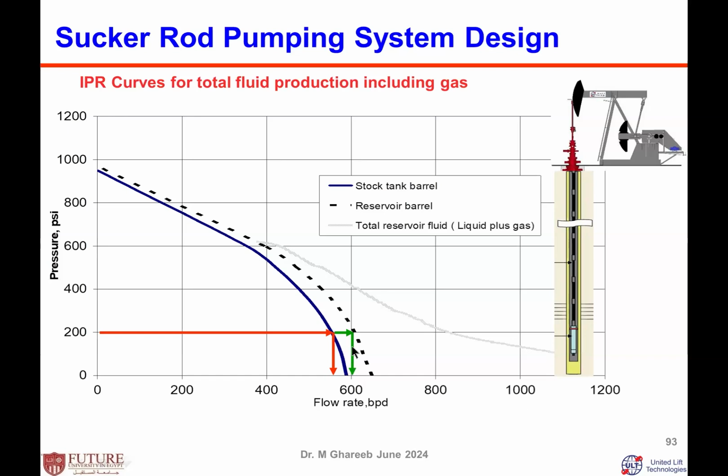This is a volume display. If there is gas and you are not able to vent the gas, all the gas goes to the pump, then in order to have 550 barrels reach the tank, this pump must displace inside the tubing over about 550 barrels per day.